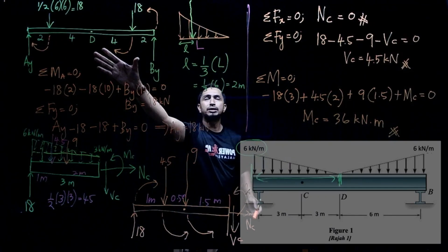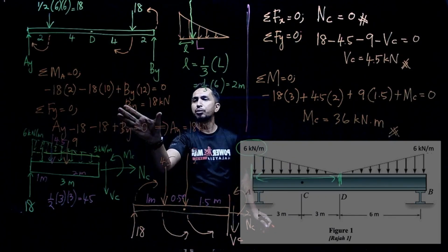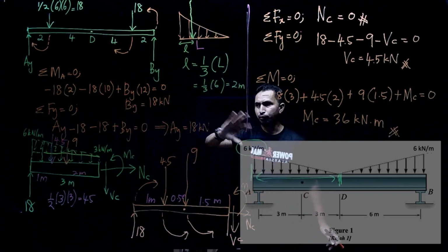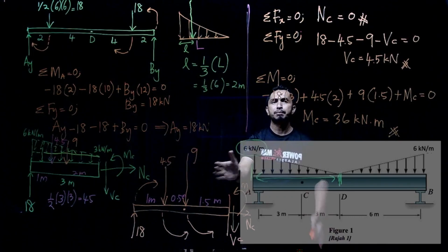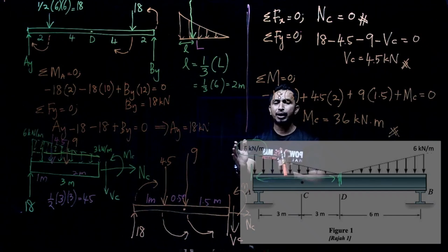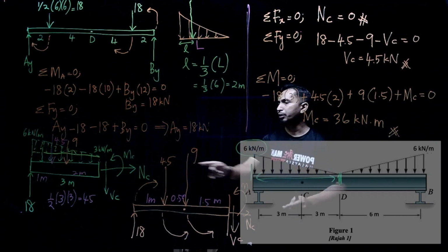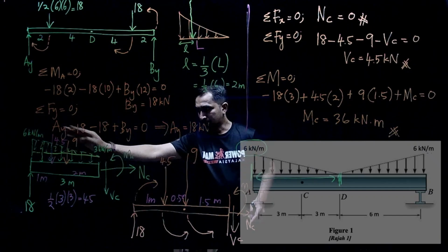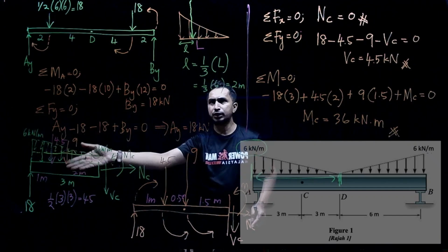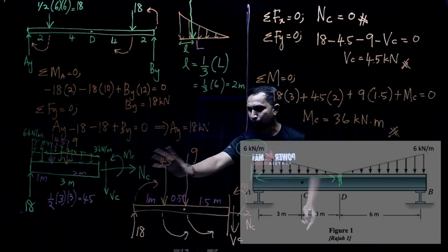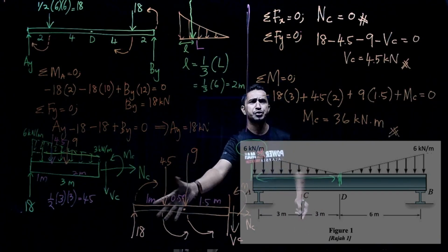First, you draw the original figure, then you find the two unknowns, AY and BY, then you move to the next free body diagram by drawing the diagram that relates to that cutting point. So this is our cutting point, point C. Convert all the distributed loading into a single load like this. Then you have all the forces and all the dimensions here.